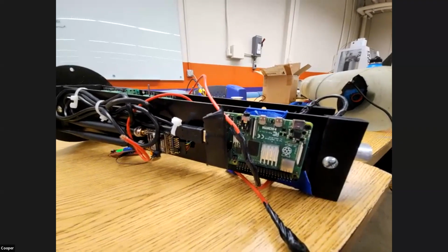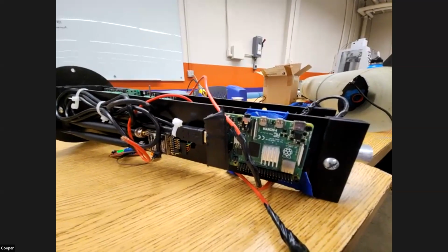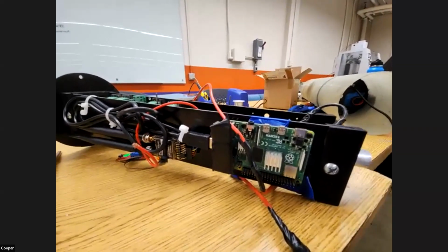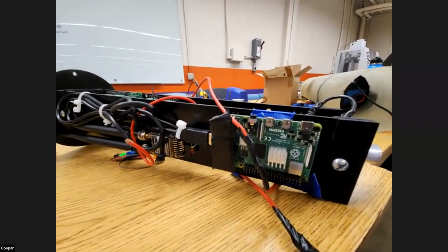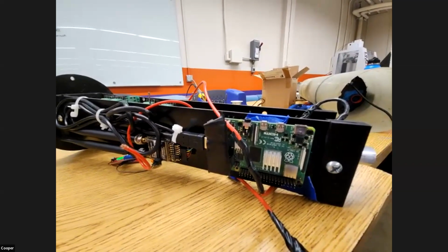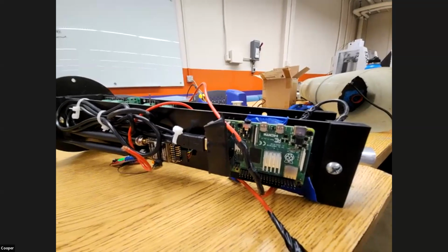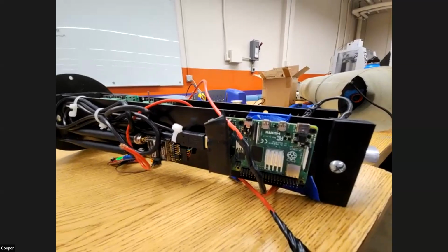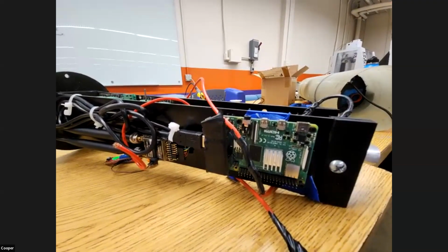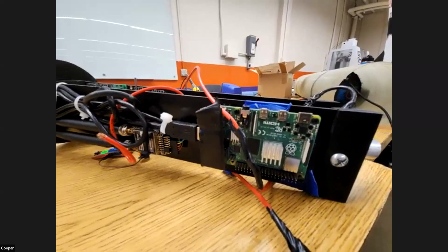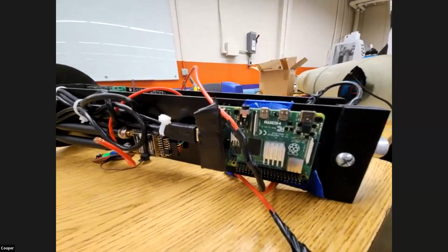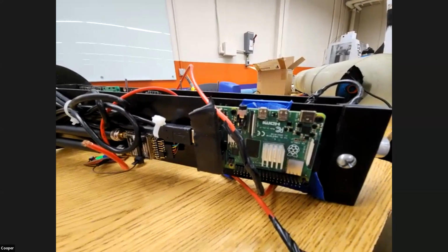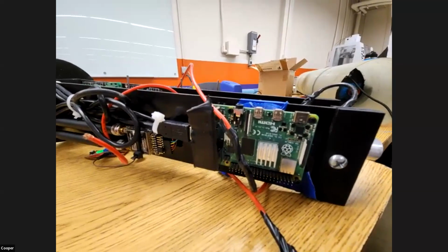Two quick questions. So when you're doing your testing, I love having a commercial flight computer right next to it. Say, for instance, you just create a small vacuum chamber, putting a COTS flight computer like that Stratologger right next to your SRAD, and then doing a compare and contrast to see how close your data looks to the commercial data. That's a good idea. Were you guys able to do anything with that? I don't think we thought of that, honestly, but that's definitely a good idea.